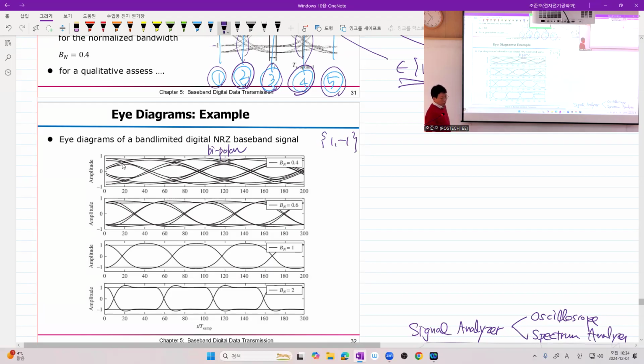Now, what would be the proper sampling offset relative to this time origin 0? 20, there is no unit, let's say microsecond, for example, then your proper sampling offset must be 20 microsecond, right? Or 20 microsecond plus some offset.